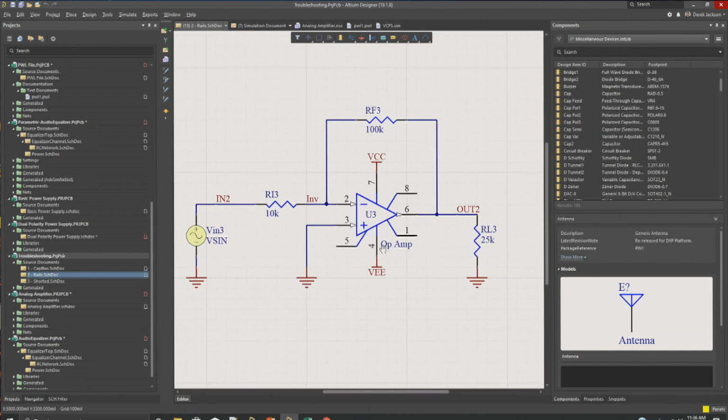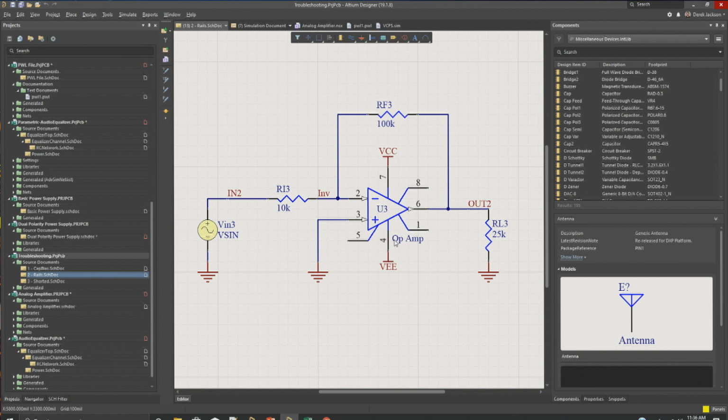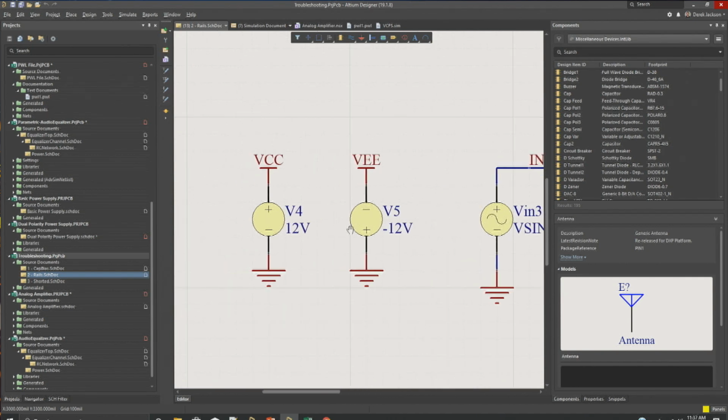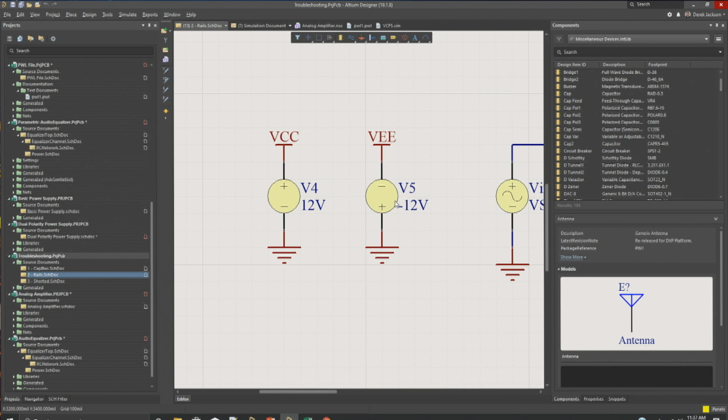Because the circuit looks fine, but inside an op amp, typically the way they have it set up, there are 2 diodes on the rail voltages. They use those diodes to drive the internal circuitry, so it requires the correct biasing. You might remember back in engineering school trying to be fancy and flipping one circuit around.